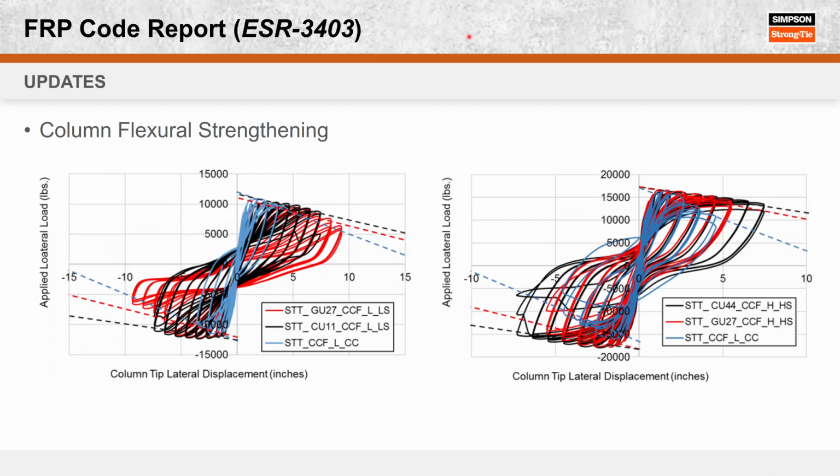You have to increase the displacement, right? So with each increasing cycle, you get bigger and bigger displacement. So instead of increasing the strength capacity in load in kips, you're increasing the displacement capacity in inches. So it's able to move more before it fails.